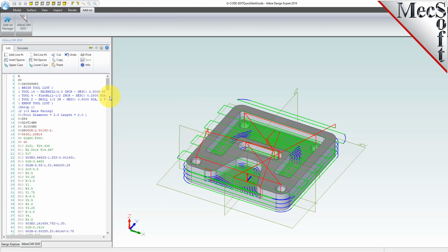Right now, let's just do some quick edits, and we'll save the G-code file. You don't have to do any of the preferences changes. You don't have to do anything. You don't have to load a tool library or tool crib. You might notice that on the project tab. All you need to do is load the G-code file, load it into the editor, and you can do some quick editing. Okay. If you notice, this file doesn't have any line numbers. Now this column on the far left is line numbers for the editor itself. Those aren't the actual line numbers that would show up in the G-code file. This column is just for reference.